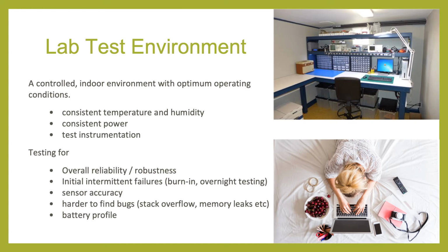In the lab, we're getting a picture of the overall performance of the device. This is where we flush out the functional bugs, which could be software, usability, or hardware malfunctions. So we're looking at whether the sensors reliably trigger and log data, and we're waiting for any bugs that take some time to appear, such as memory leaks, stack overflows, or intermittent solder joints. In the lab, most failures occur within the first few hours, so a common practice is to run devices overnight in a burn-in test. We're also using the lab to start building a real-life battery profile that we can use as a basis for the field.